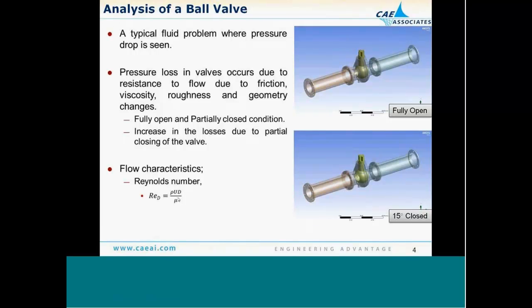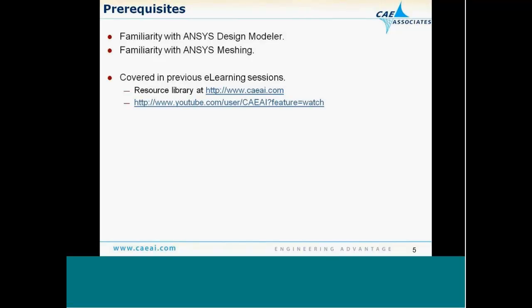The reason we consider the Reynolds number is that if it is sufficiently high, the flow can turn turbulent. Typically for a pipe flow, the critical Reynolds number is around 2300. In that case, you need to make sure that your model also considers turbulence when solving the problem.